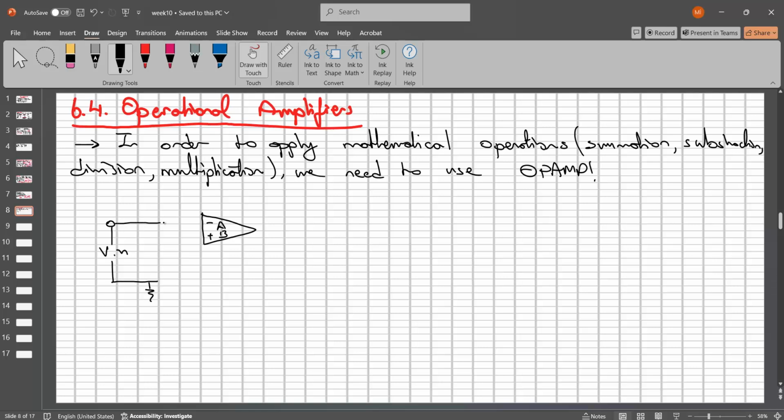And so this is going to the minus attachment in here, right? And also plus is connected to the ground, right? And we should give the resistance in here, just like this one, Ri, and also we should give another resistance at the end of the op-amp. This is V out. This is the RF, right?